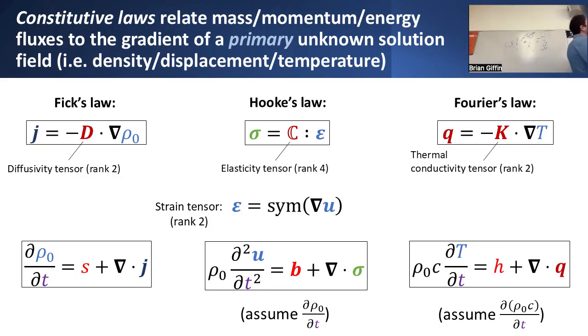In a more general sense, we can come up with some multi-dimensional relationship between stress and strain that characterizes the fully three-dimensional deformed state of material. In fact, it turns out that the definition of strain can be related back to a gradient quantity of the displacement field itself. So also in direct analog, the stress depends on some set of material parameters multiplied by the gradient of the displacement.